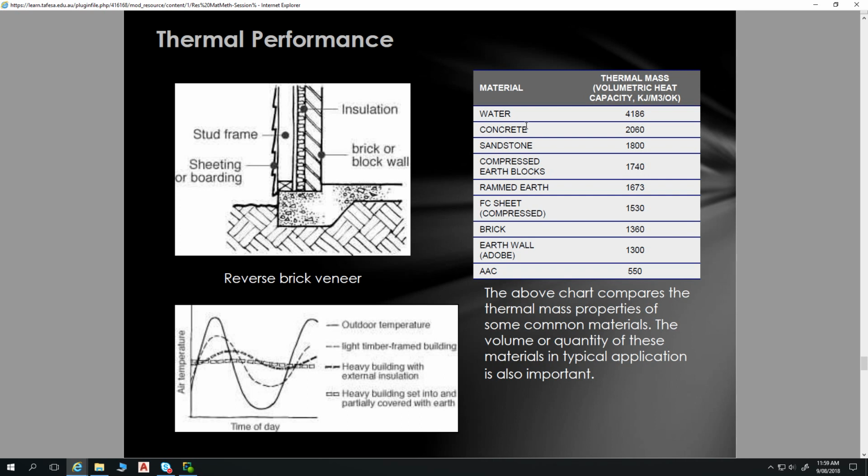But that wouldn't be the best idea on the western wall, though, would it? Because if you're getting a heat transfer through the cladding, yeah, a certain amount's going to go through the insulation into that block wall. Obviously, if it's a western wall, in summer it's going to be a lot hotter, to dissipate heat into the house. Exactly.